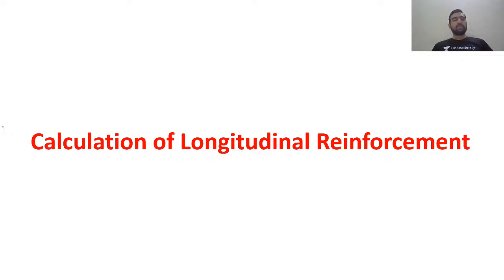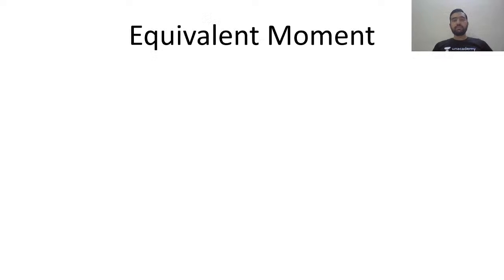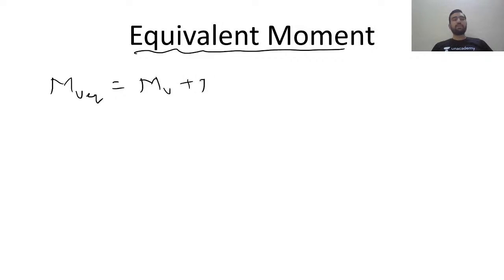Next is step number 2, which is calculation of longitudinal reinforcement. So guys, how are we going to calculate longitudinal reinforcement? Just see. First of all, we will calculate the equivalent moment. How can I calculate the value of equivalent moment? Mu equivalent is equal to Mu plus Mtu.